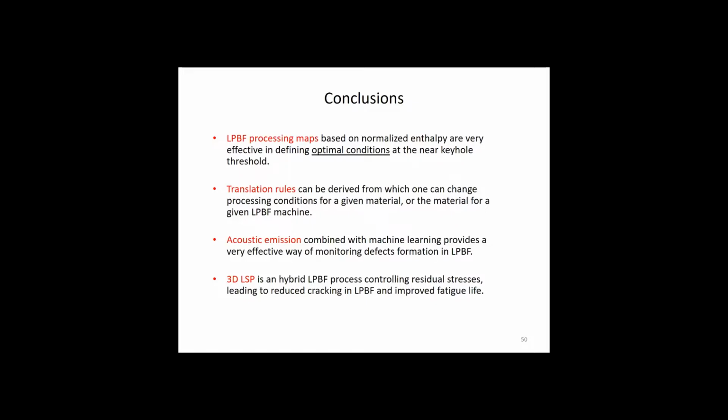Acoustic emission is also an interesting method for monitoring defects and distinguishing in particular the different types of porosities. We also want to apply that to the cracking phenomena. And then if we identify either porosity or cracks, we can try to heal them. One way of healing cracks in a nickel-based superalloy would be to use the hybrid process, combining laser powder bed fusion with laser shock peening.